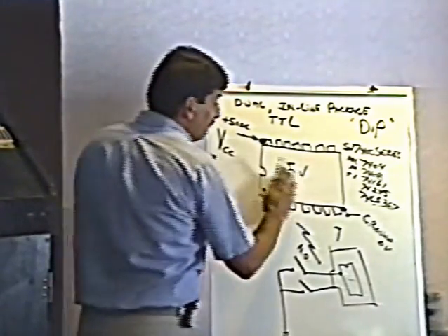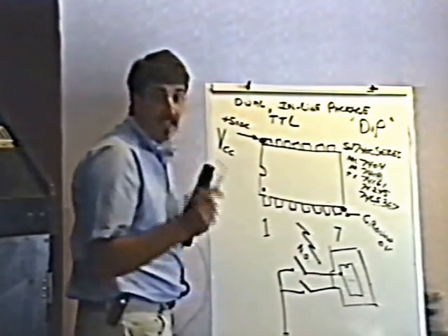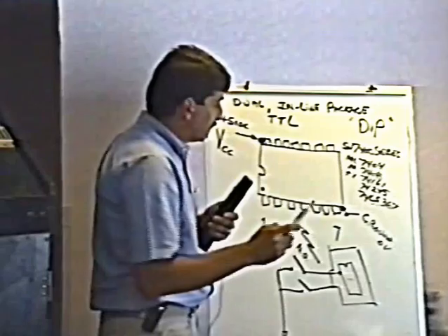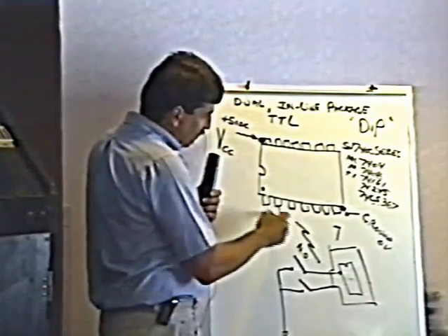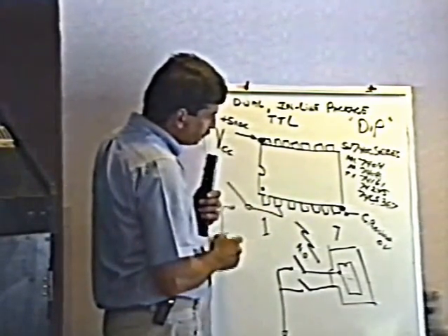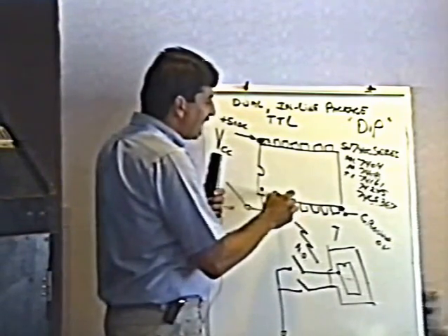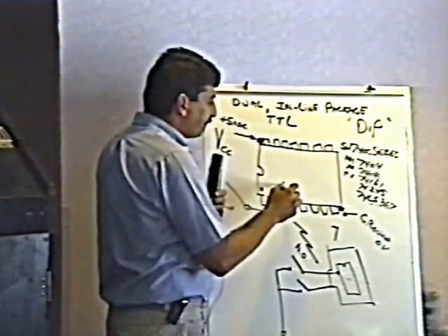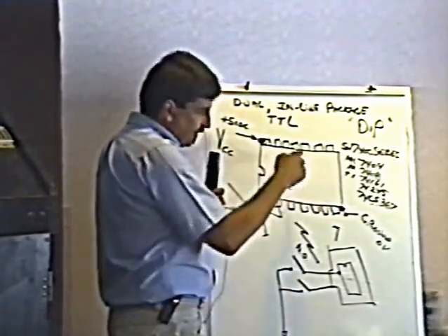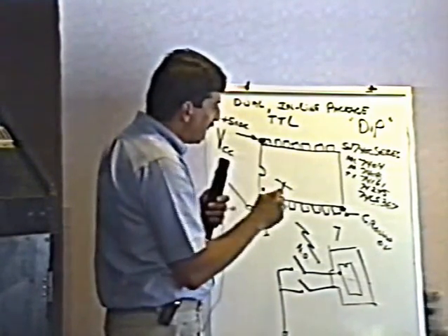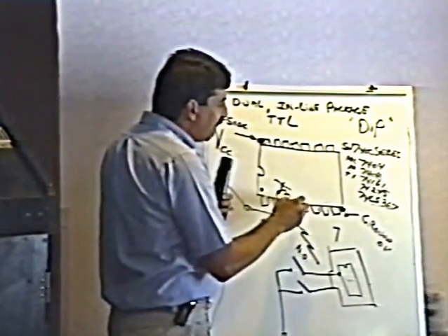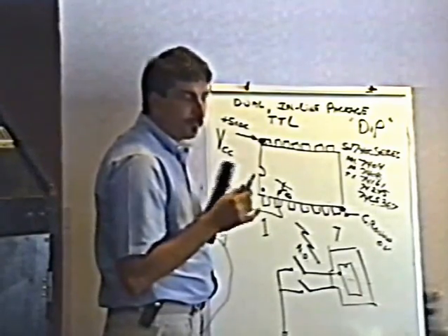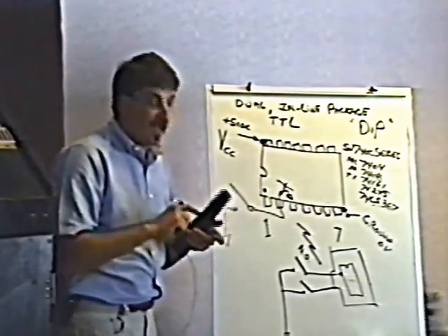What it does, though, fortunately in a way, is that the inputs almost always short circuit. Let's say that this goes to a switch somewhere like this. Inside this chip is a mess of transistors, thousands of them, really. And what happens is this input will short to ground. The symptom that you get is this.